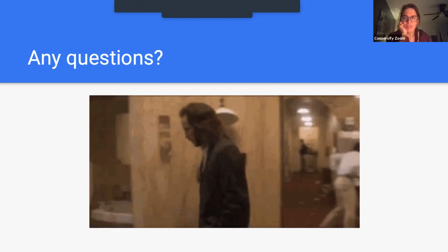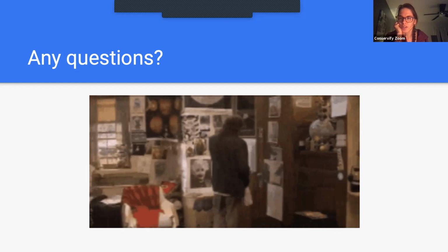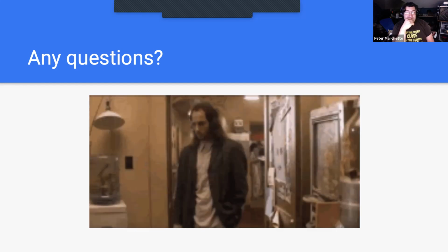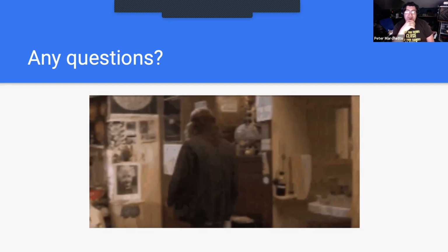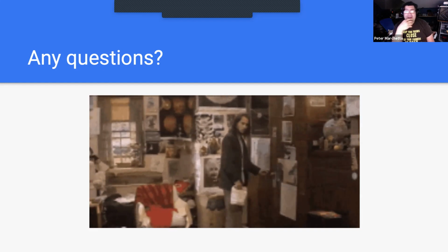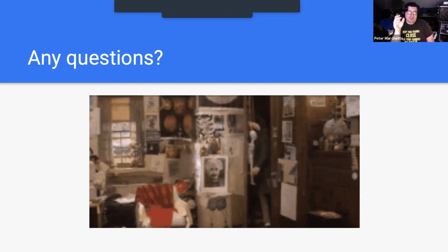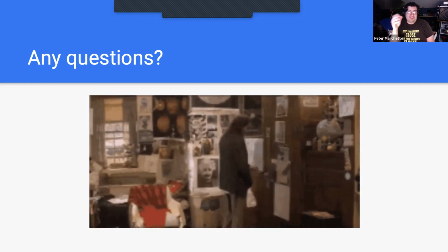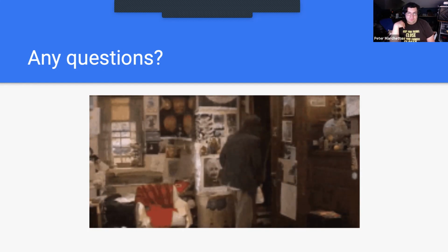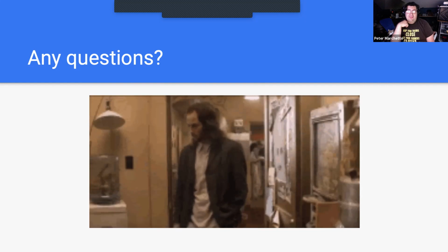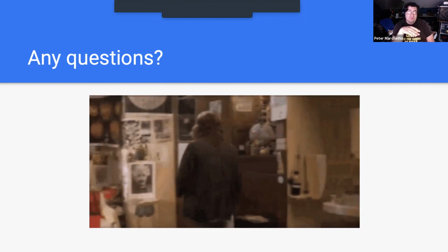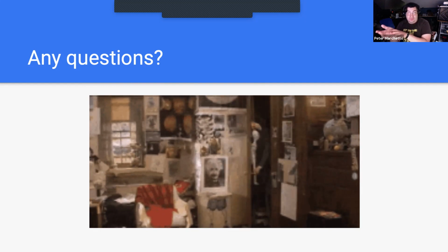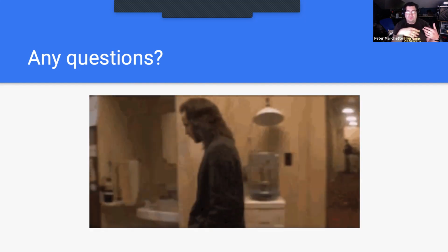Yeah, that's interesting. That's what I was going to ask, is that with 3-point calibration, it's not always a linear situation that you end up with. Exactly. And for that matter, technically speaking, from a mathematical perspective, you actually want to try for 4 points or more, because establishing linearity versus nonlinearity for a function mathematically can't really be done with only 3 points. The thing that we have working in our favor that allows us to do 3 points is that we're working with pretty well characterized sensors from the get-go. And because we know what family of functions we should see, that allows us to get rid of one of those points.